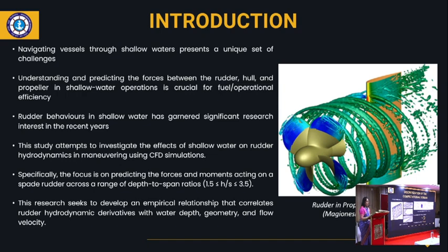We conducted a grid independency analysis, which gave us 2.9 million cells as the optimum. Of course, as was asked previously, a higher grid size gave us a better value, but we looked at the difference between the values and the computational effort we were putting in. We thought we should go for not 3.2 but 2.9 million. So this is a mathematical representation of the boundary conditions.